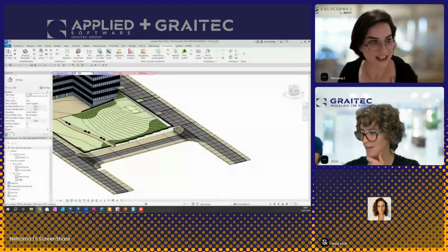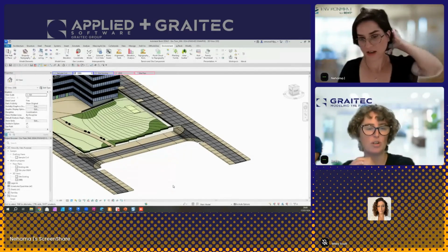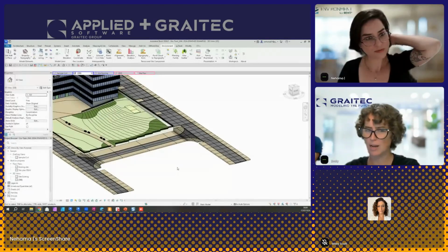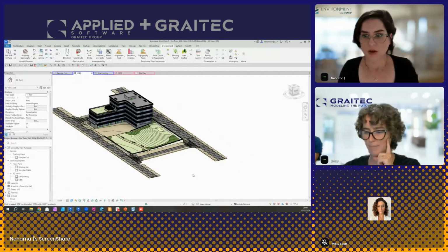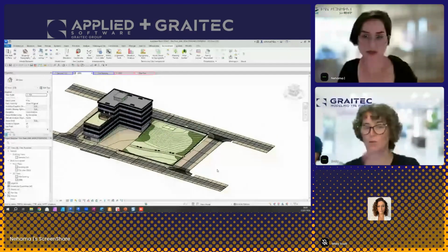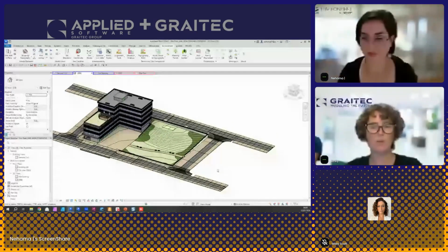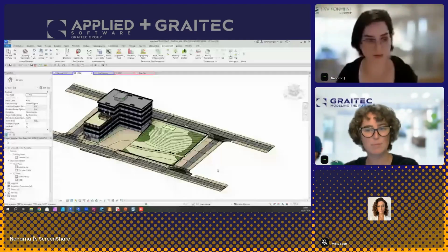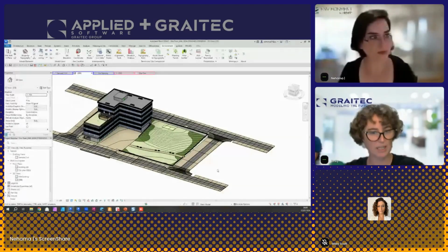So hopefully you guys can give us some feedback on whether you understand that reference surface, because it is kind of important to everything else you're going to be doing in Revit. And this reference surface was introduced in 2024, I think. And so if you're still in an older version, environment was referring to it as a help surface, right? So when you made a topography that you then hosted other elements to, like your floors, it's similar to that, but it's now embedded directly in the topo solid object.